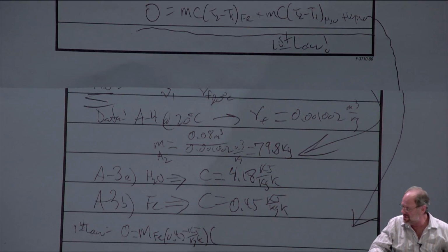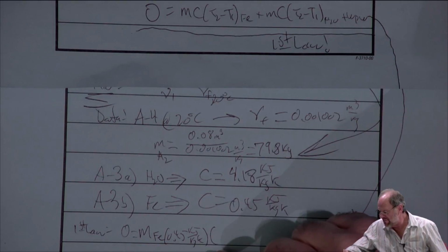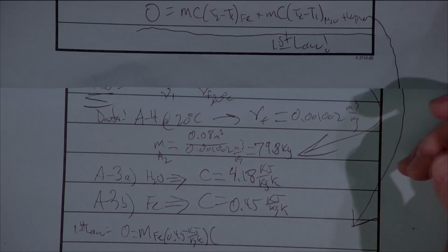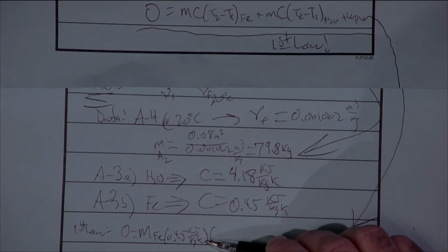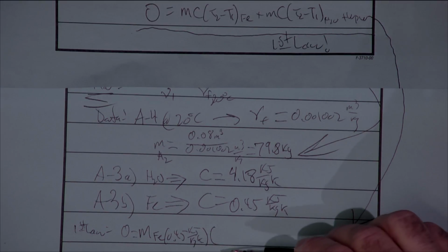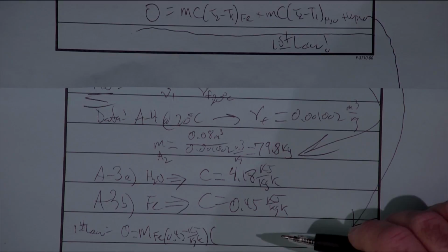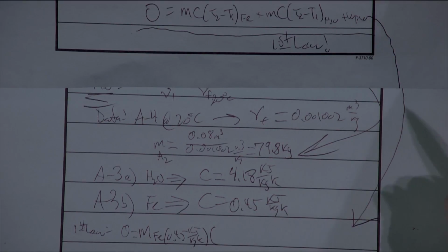And here's another thing that is worthy of a little discussion. I really should be using the absolute temperature scale. After all, my units are per degree Kelvin, right? However, I'm finding a temperature difference in this problem. I'm not using an actual temperature. I'm using a temperature difference to solve this problem. So isn't the temperature difference in Celsius the same as the temperature difference in Kelvin?